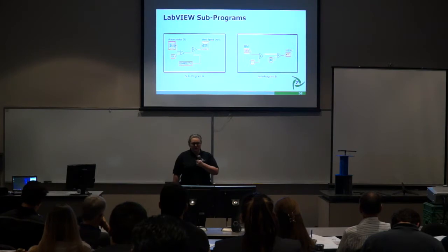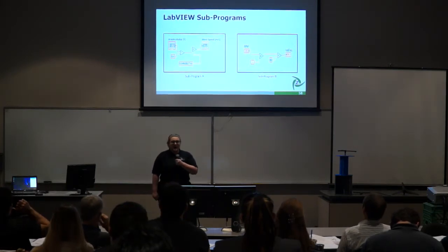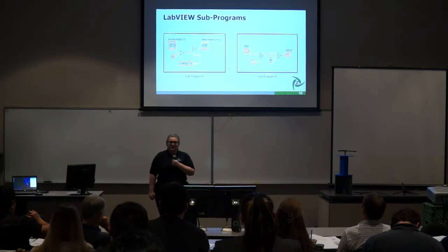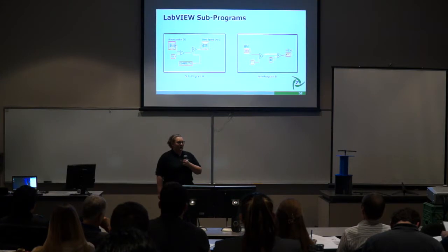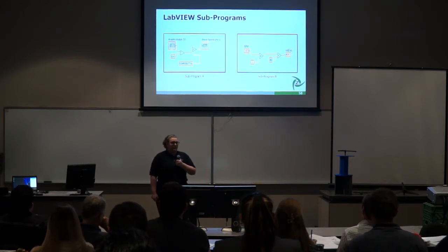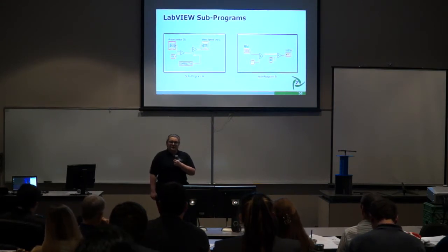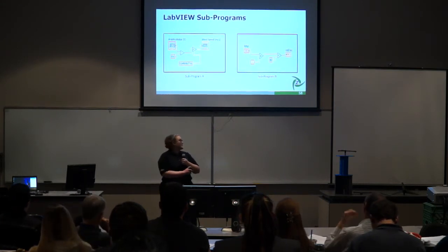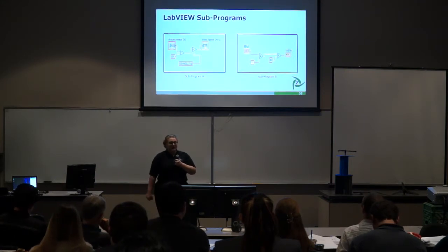These are the 2 subprograms. On the left is subprogram A for the anemometer. As the anemometer has a voltage output, this program converts the voltage output into a wind speed in meters per second. This is based on the published data correlation from the manufacturer's data sheet. On the right side of the screen is subprogram B. This simply converts the revolutions per minute into radians per second.